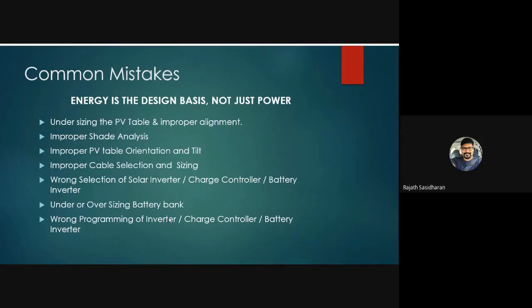improper cable selection and sizing. For DC, single stranded cables are used because the current flows through the entire cross section of a cable. But in AC, it more or less goes through the outer surface. It's called the skin effect. So we use multi-stranded cables there.